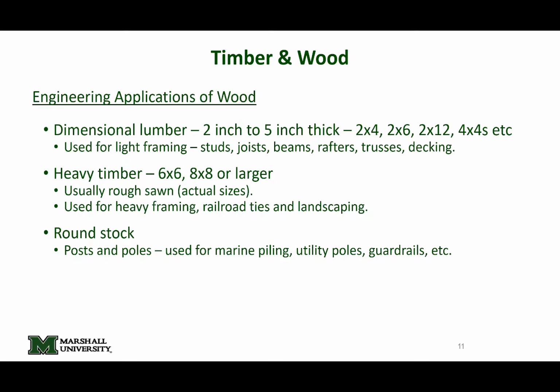Okay, and engineered wood products are things like plywood, OSB, glulam, CLT, and really the difference between an engineered wood product and sawn lumber is the introduction of glue. If there's any sort of glue or adhesive that is brought into the manufacturing process, that's what it's for. We'll talk a little bit more about that throughout today's lecture.